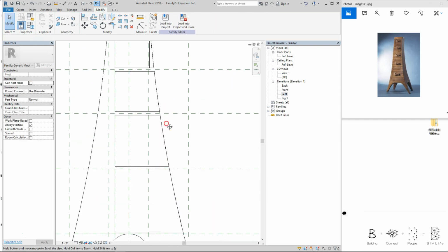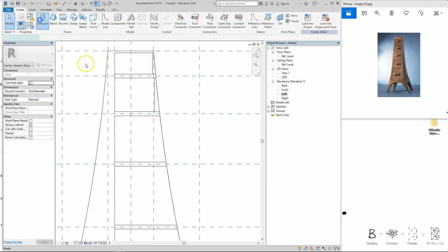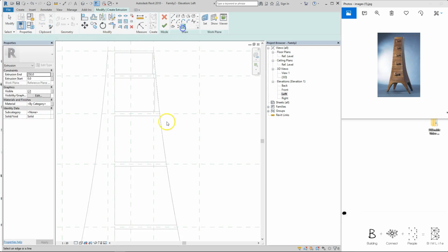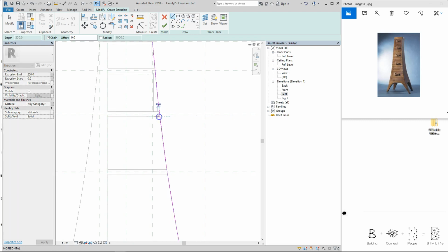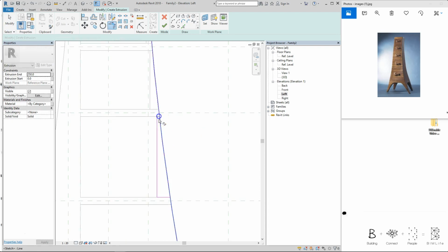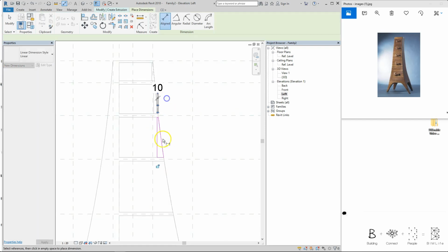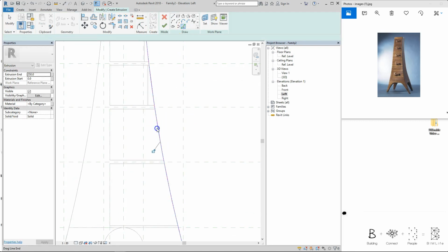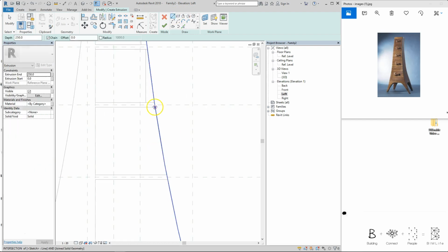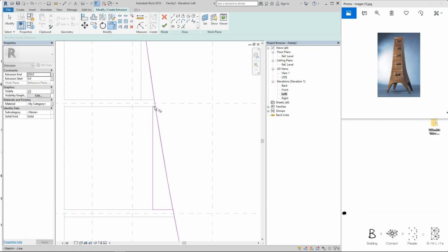And we're going to do this for the third, fourth, and fifth drawer, so it's going to be a little bit faster. Pick lines, pick the curvature, draw a line from the top, 10 mm, to the bottom, trim it, align it, make sure that is 10 mm, press the green tick, extrusion command, this, lock it, draw 10 mm, basically the same steps.